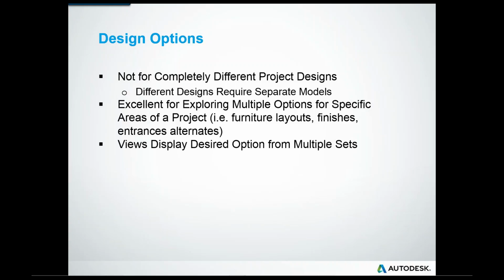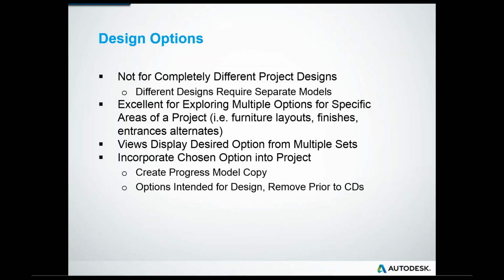And you can set views for those options. Now, I have to tell you, one of these also can be incorporated ultimately into your chosen option, basically your first choice, your primary option as it's called in Revit. And then the other options, let's say we have option 1, 2, and 3. The owner decides to go with option 3. The other 2 options will be automatically removed from Revit. So there's no remnant of it.